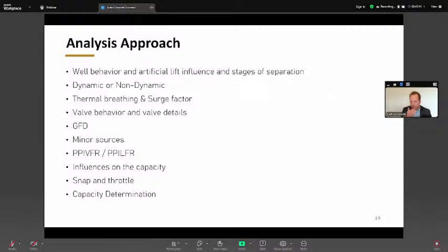If you have on the front end, your first stage of separation, these big snap acting valves, so basically a valve that opens really quickly and you get this surge of fluid. Most often you see that on the first stage of separation because most of the flow meters in the oil field actually need a constant flow. You can't have a throttling flow through that to get accurate metering. And so you have this big snap valve so that you can get that flow measurement. And then your secondary stage, maybe that's a throttle valve. It just opens as fluid comes in. Well, that governing flow device would basically be that snap valve. That's what's dictating the behavior that's going to be going to your tanks.